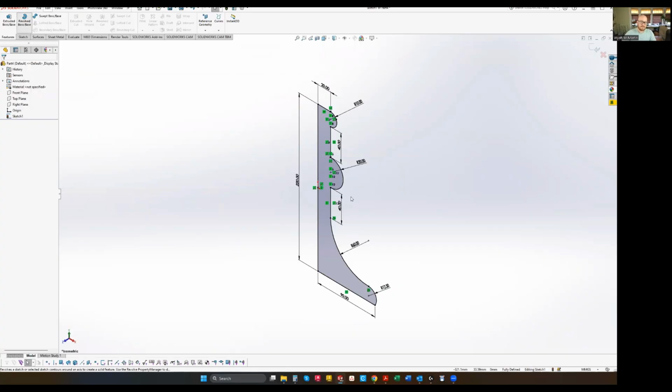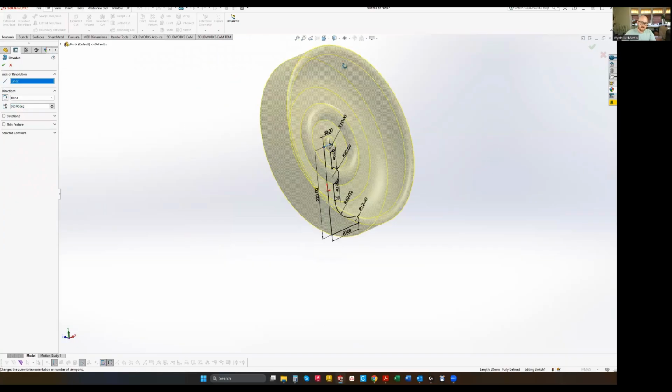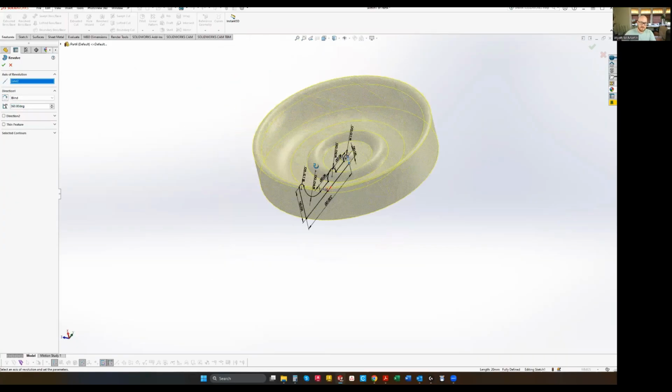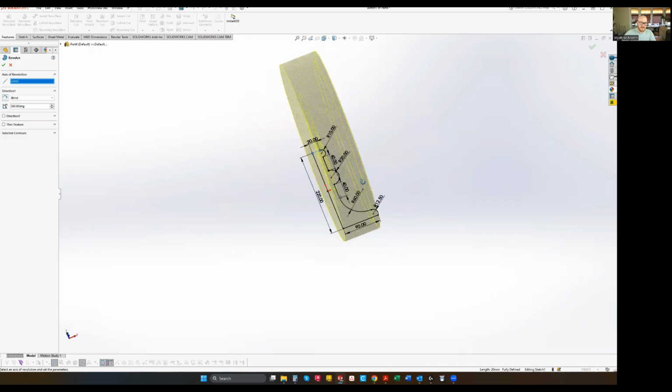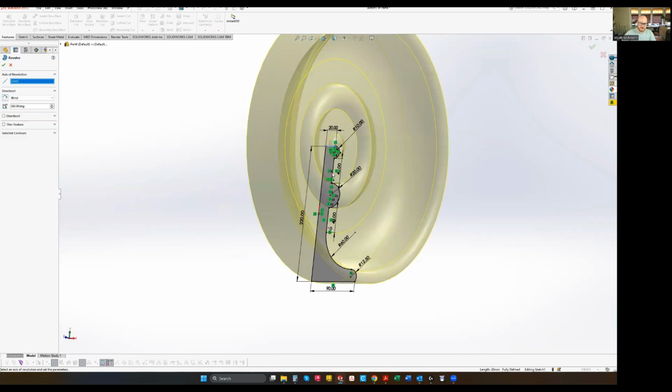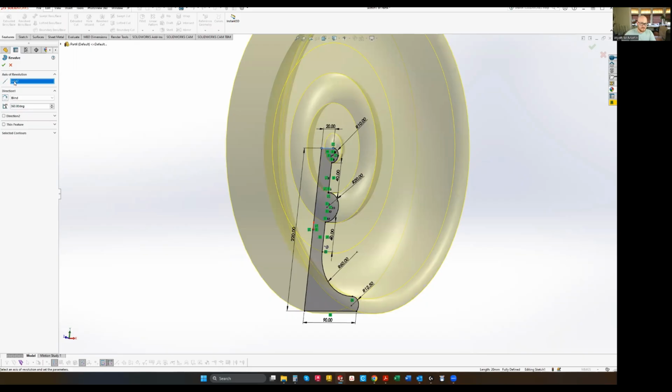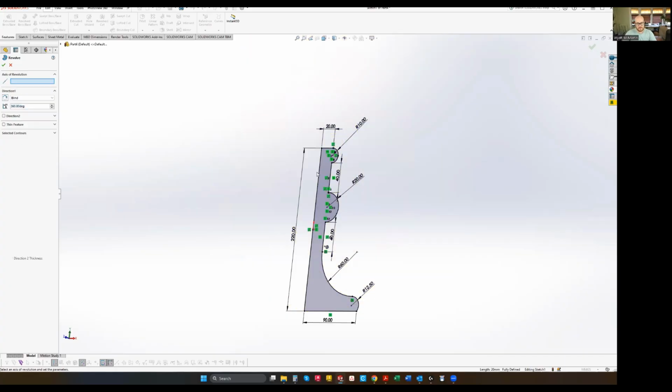That allows us to take a profile and rotate it 360 degrees, or revolve it around an axis. So if you accidentally click the wrong axis, for example, if I accidentally click this line here, it's a cool bowl shape, but that is obviously not what we are trying to accomplish. If that happens to you, just click on line 2 in the axis of revolution and click delete. And then you can reselect this line.